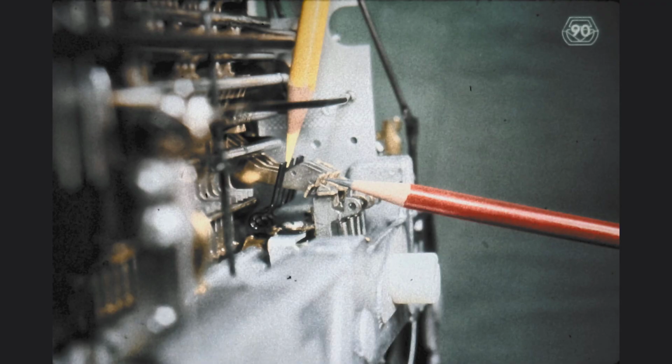Finally, we have to adjust the amount of keylever pawl front-to-rear overlap with the interposers. This front-to-rear position of the keylever pawl is adjusted by forming the guide fork indicated by the yellow pencil. In older models, we might encounter adjustable screws instead of these forks, but whatever the hardware, the overlap should measure approximately 1 mm for all the keylever pawls. It is permissible to allow 1.5 mm of overlap in the case of the index keylever pawl.